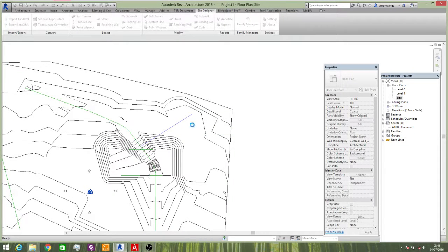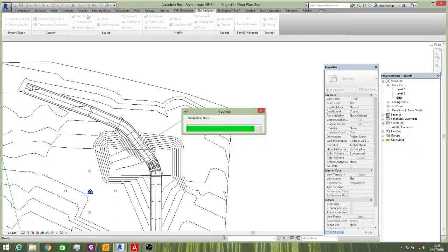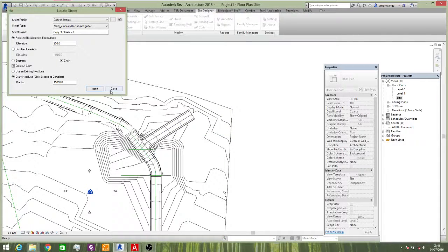So it's actually a conceptual mass. It's also important to know that once you close your project and reopen it, masses are not always shown by default, so you have to go back to the massing environment and show your masses so that you can be able to see this mass. It's not an object as such, it's a conceptual mass.